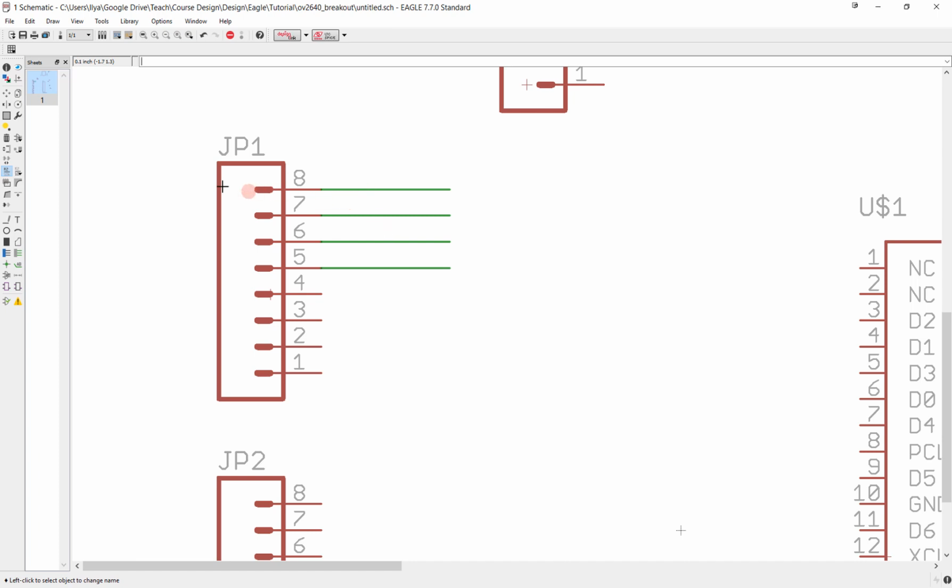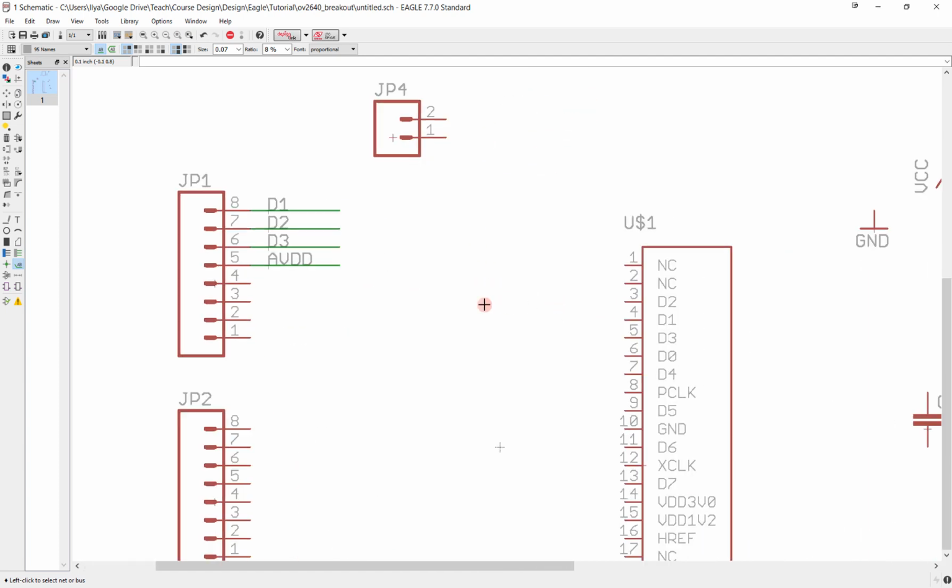So then you're not sure which one is actually which after a while because they're not labeled. So one thing you can do here to make this easier on yourself is click on this tool right here, the label. And then if you click on this, you can actually place these labels associated with this wire somewhere where it's going to be helpful to you. So let's say like this, and again I click on each one and it's going to show what it's named. Now to make a connection using this, I would once again, for example here, make the same kinds of wires. The length doesn't really matter. I'm making it kind of arbitrary just to illustrate this.